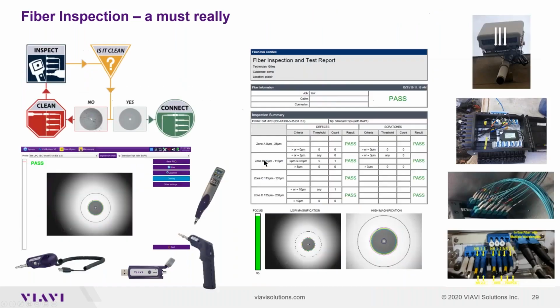One of the last slides is this fiber inspection. I only want to mention that you really take care. If you have a 400 gig with 4 lambdas inside, each carrying 100 gig, and you don't take care of the optical connector, with a little bit of dust on the connector like this, you will make a very hard life for this forward error correction, because it has to correct many more errors than in case the connector is clean.